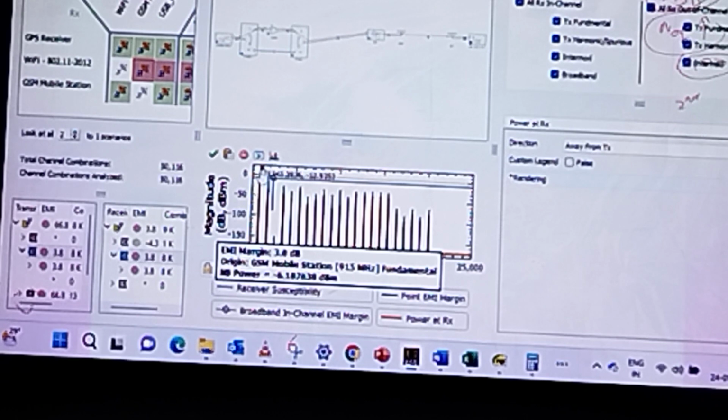Actually, in this particular case, on the first band itself, it is crossing the EMI margin. So again we need to suppress this by 20 dB or something here. Now this second band has been switched and decoupled. The second harmonic has been decoupled, but still this is crossing the EMI margin. Because of that, the linking is again here. So here you can set two stop bands, another filter which will be taking care of this particular EMI margin. Basically, this is how we will go.